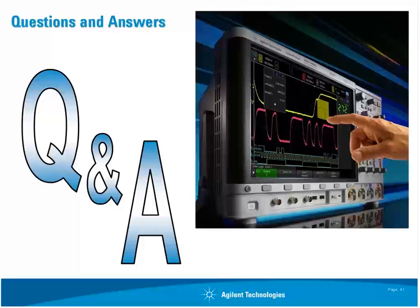Next question, what is the rearm time for segmented mode? On the scopes that I showed here today, our InfiniiVision 3000 and 4000 series oscilloscopes, the minimum rearm time for those scopes is 1 microsecond.